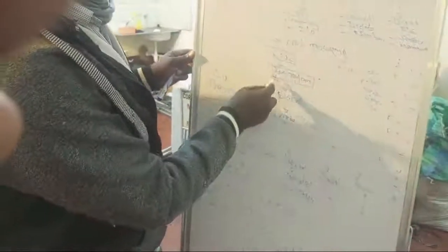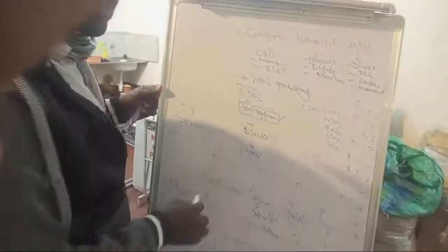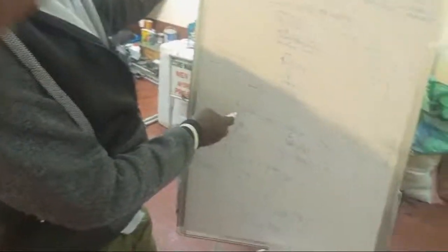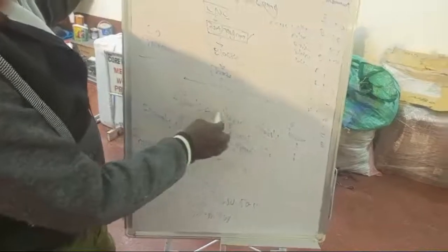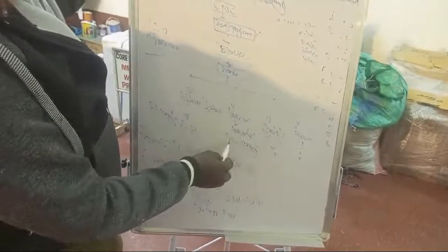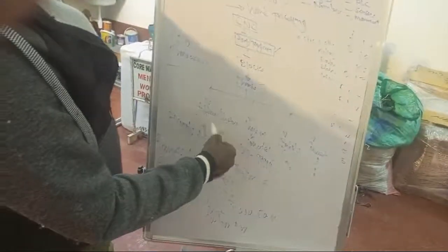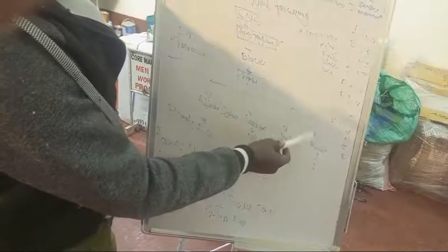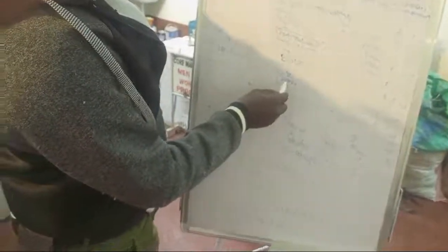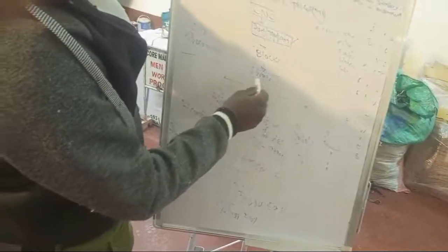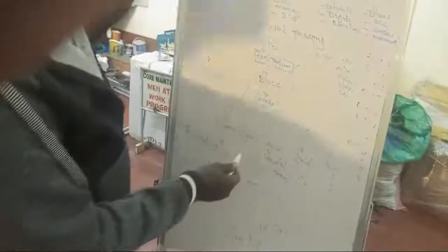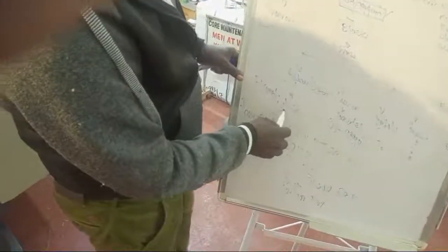So this part program contains what we call blocks, and these blocks contain words. In each word we have either an address or a letter, numbers or digits, which range from 0 to 99999, symbols, and comments. Putting all this together, numbers, address, symbols, comments form a word. Many words in a line or block form a block, and many blocks form what? A part program. A simple example of an address or a letter is A up to Z.